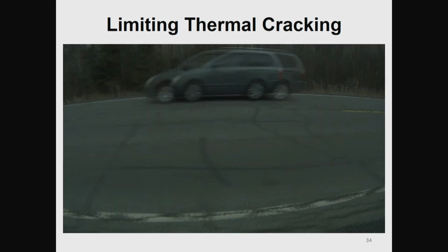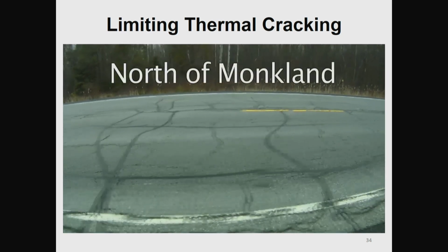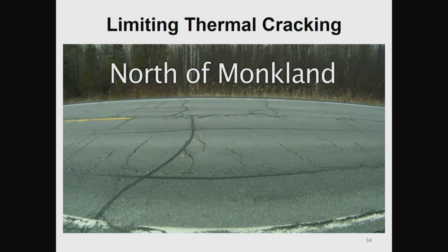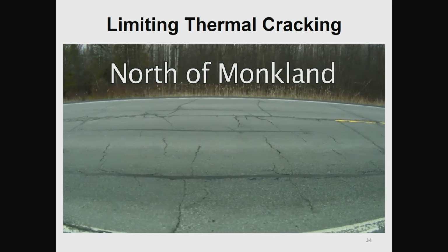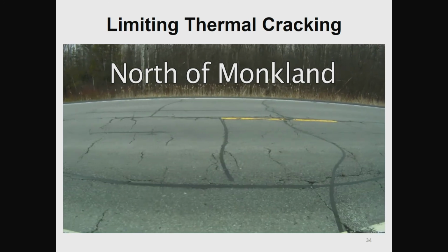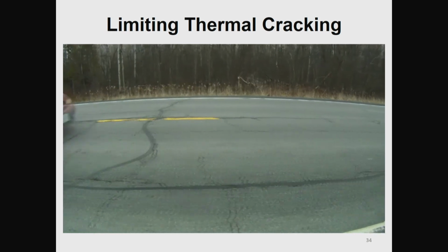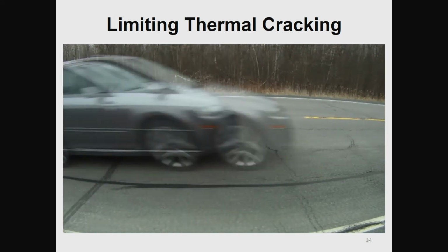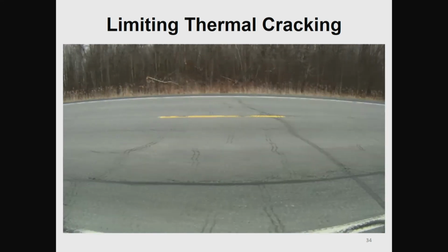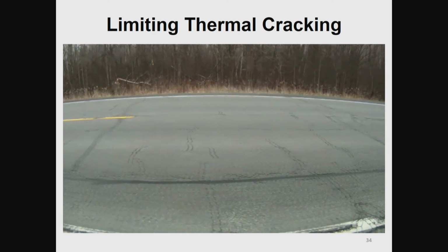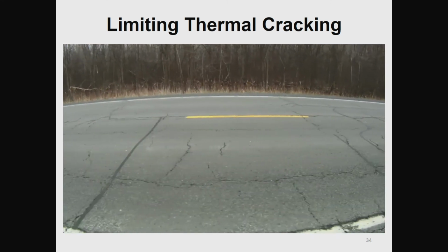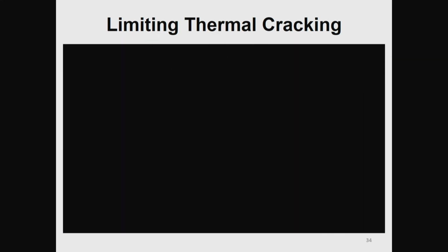The same design, the same road, adjacent to it. This is 12 years old, and this has a little bit of motor oil problem. It was sealed for 66 kilometers of cracks within the first 5 years. But as you can see, the sealing didn't help too much because it's cracking in between. So this is only 2 years older, it's 12 years old. So this will last about 15 years, and then they have to replace the whole road. It's hopeless, it's a disaster.